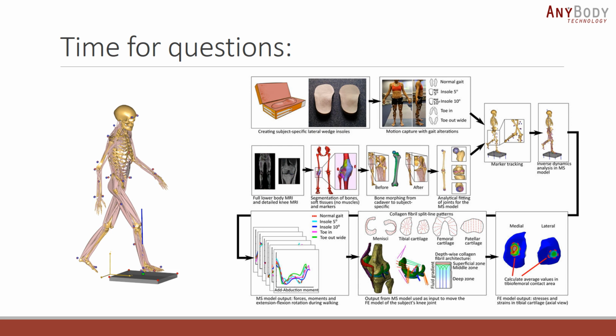There's also one person that asked if you used hexahedral elements or any specific software for the FE modeling. Oh yeah, so we use hexahedral elements, the C3D8P model. So it's a porous cube essentially, with 8 nodes and 8 integration points. And what was the other part? Yeah, and if you used any specific software for doing the finite element analysis.